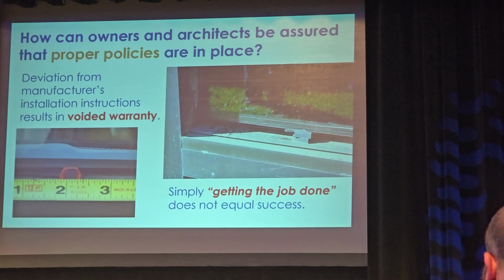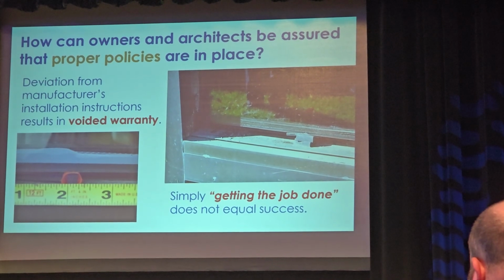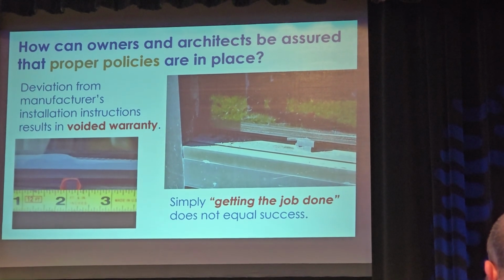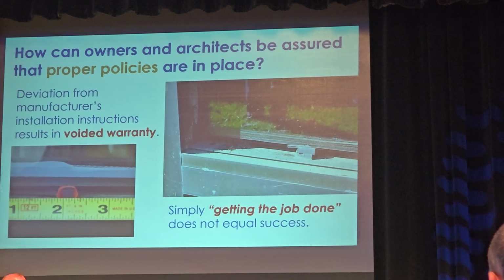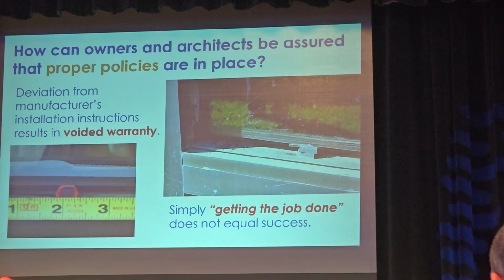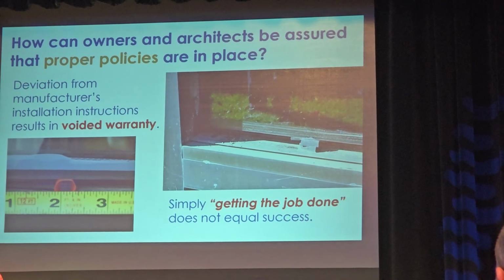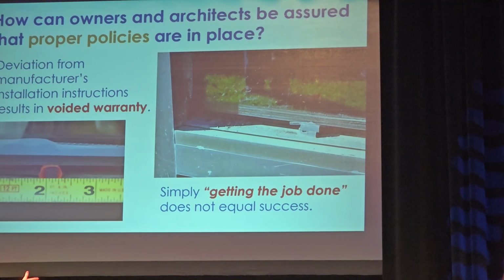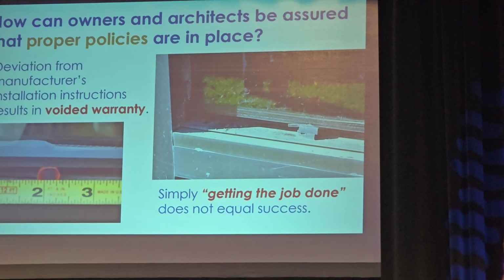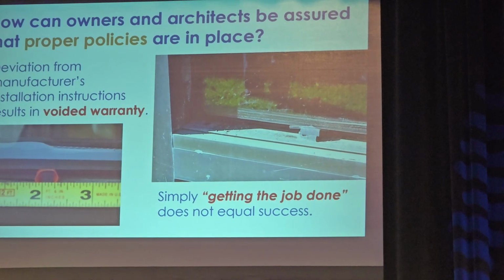Doug, anything else to elaborate on from the photos up on the screen? Yeah, again, in this storefront picture up here, stacking setting blocks, that's fine. But the way they're stacking here right now would restrict the glass stop from closing the system up.